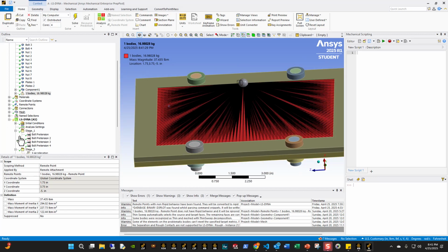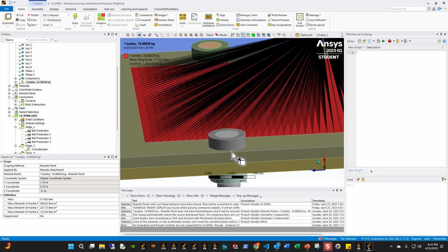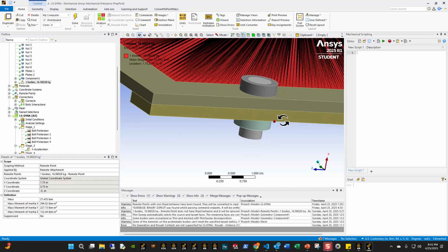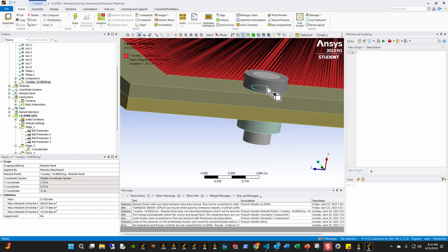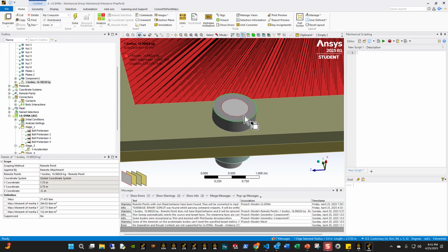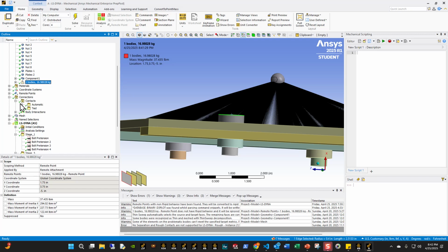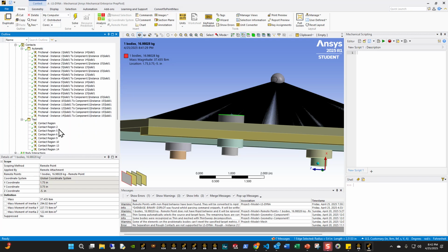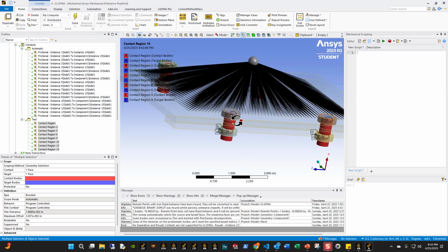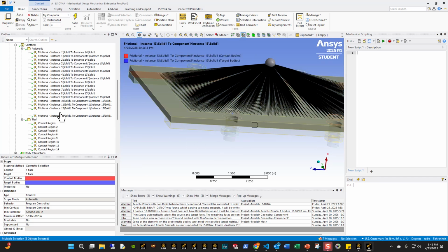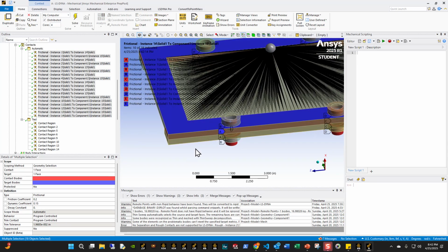And then the model itself is set such that you essentially have what you expect the bolt to be. Basically, there's friction between this set of plates. There's a bonded, tight contact between the nuts and the bolts, and everything else is going to be a frictional contact, like an automatic contact. You can see the way I have it set up: the only places where we have tight contact are between the nuts and the bolts. Everything else is going to be an automatic, frictional or sliding contact.